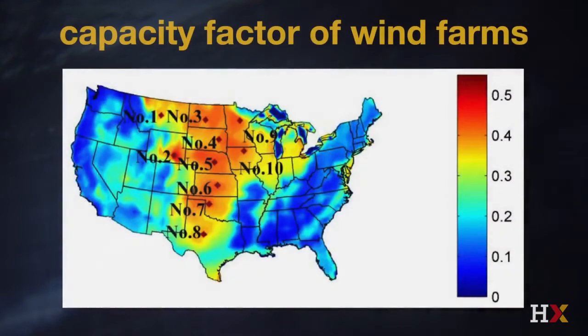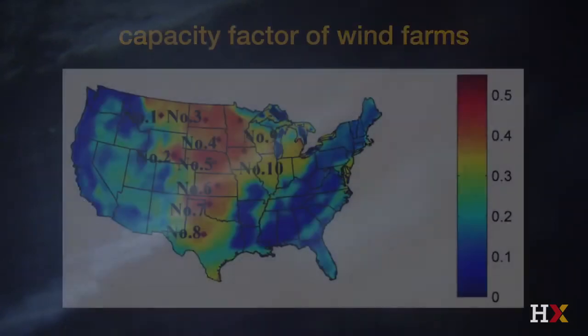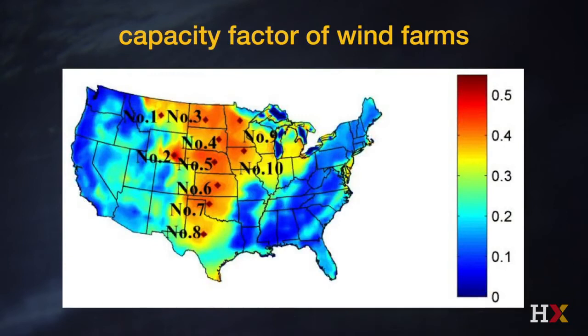That means a capacity factor of 0.5 would produce day in, day out 1.25 megawatts of power. Now, a capacity factor of 0.5 is remarkably high, but if we analyze the central part of the United States, for example, and I can do this for China or any other region, the capacity factor throughout the entire central part of the U.S. runs between 0.4 and 0.5, and that's remarkable.